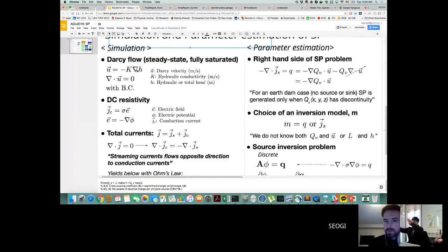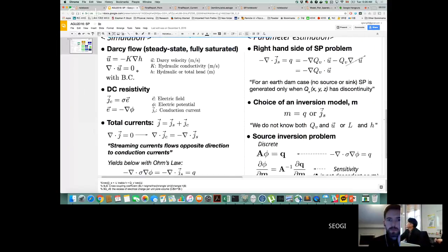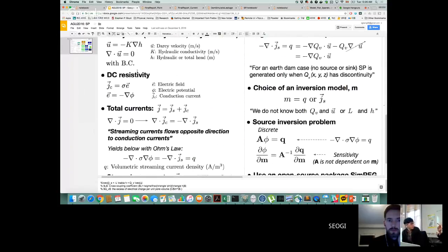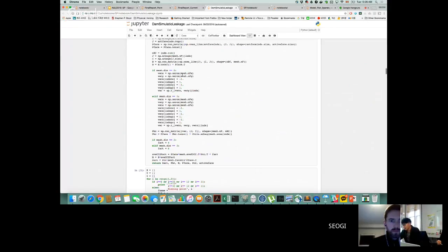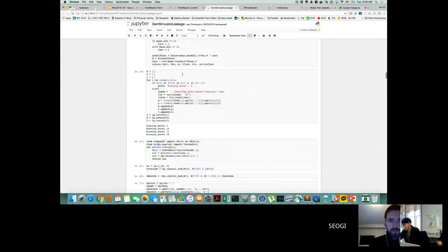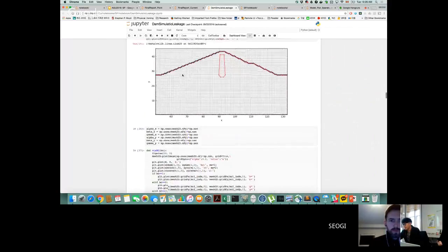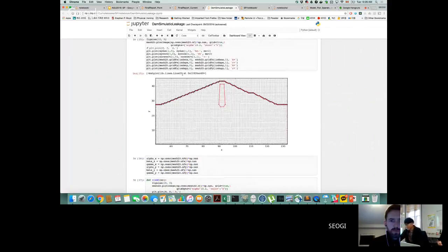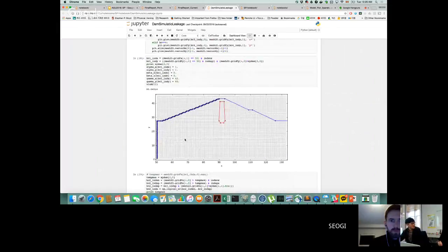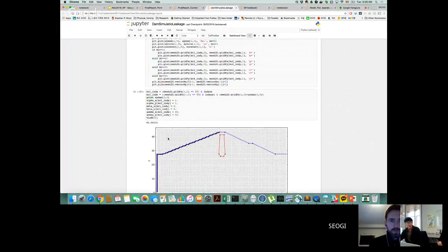So I usually put the Dirichlet on each side, and then for the top at the moment. And when you say that, because your mesh is actually like a staircase, right, so on these faces it's Neumann, and then these faces. Right, so you need a little bit of thought about those types of things, and you need to do this kind of thing. I have a little bit of utilities that does it.